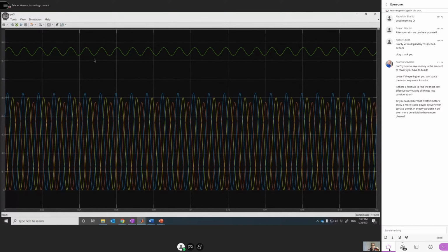But as you can see, the oscillations are not as high as in the single phase. So in the single phase power, the power oscillates from 0 to near 0.5. So the amplitude of oscillation is 0.5. But here, it is limited. But still, we have oscillations. Okay? And that is why we try to reduce the system imbalance, try to make the voltages and currents balanced. And I'm going to discuss all these concepts when I introduce three-phase circuits. I'm sure that you have studied this in the second year, but it is good to remind you about it and also introduce it from the power system perspective.